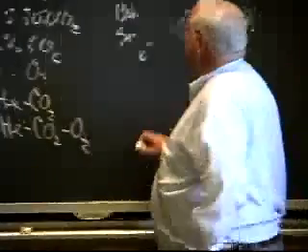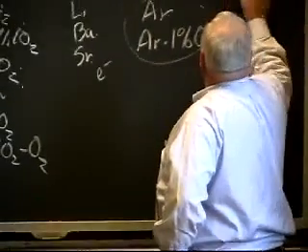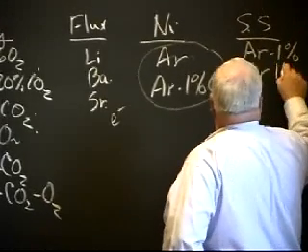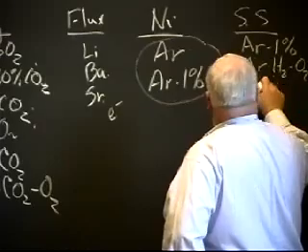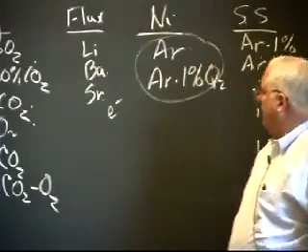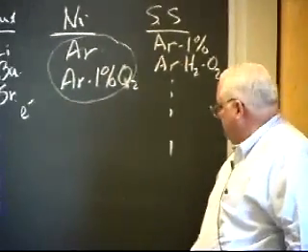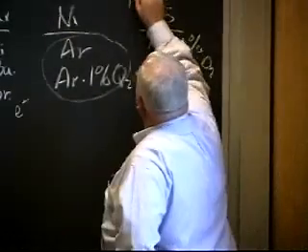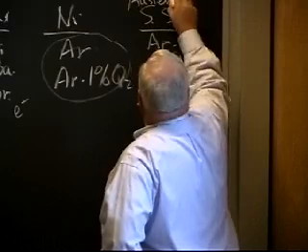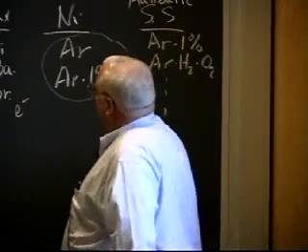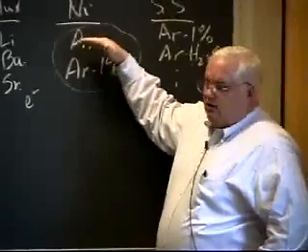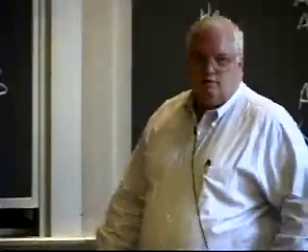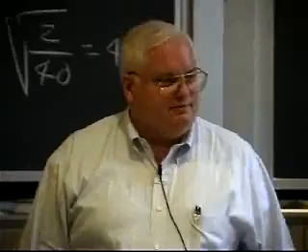If you're going to stainless steels, you can use argon oxygen, you can use argon hydrogen oxygen, and essentially almost everything else you use over here for carbon and low alloy steels. If you're talking austenitic stainless steels. If you're talking ferritic stainless steels, you can't use that, so this is really austenitic stainless steels. And you can talk about titanium. It's very reactive. You got to use argon or helium, so far as that goes. And it's shielding gas. Okay? Does that answer your question?